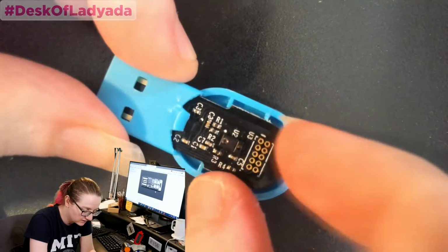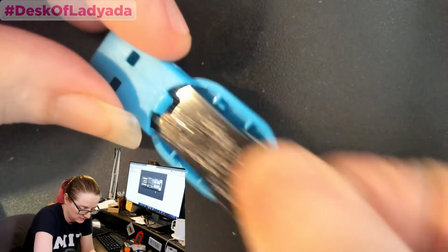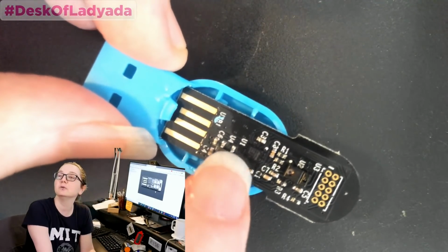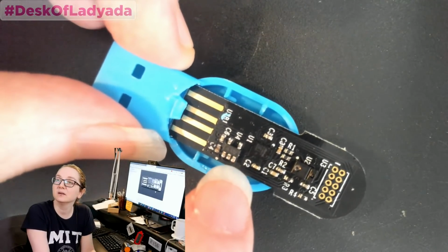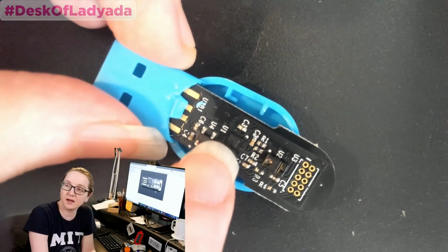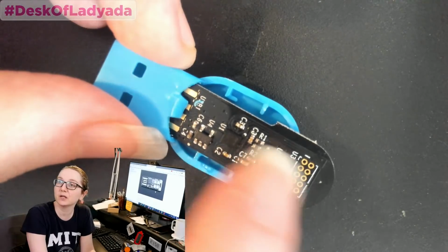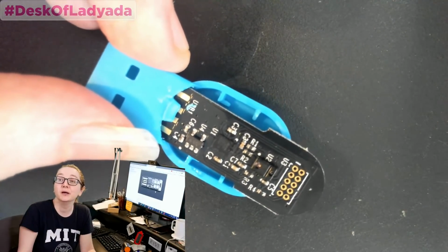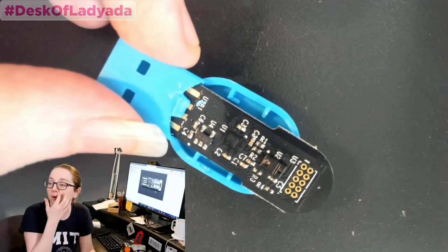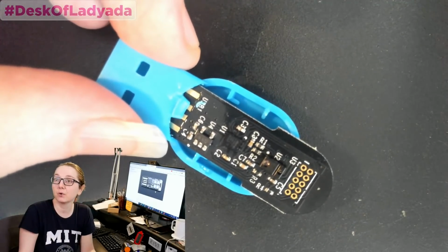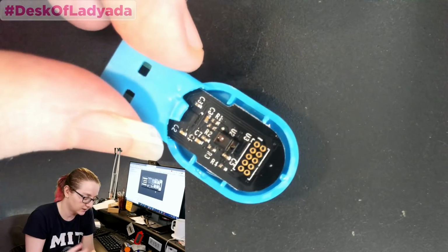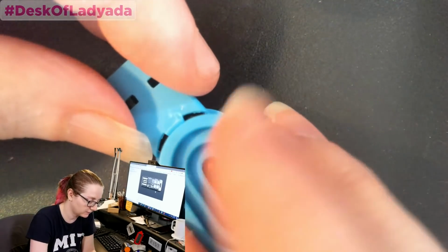And then underneath here, if you pull this up, they use my favorite AP2212 regulator, which is totally overkill. So they probably used it because I use it. And then here is a SAMD21E16. So this is running Arduino code. I know it's running Arduino code because the VID is Arduino, so they didn't change it. They may have used the Trinkey core, or they might have created their own core. I don't know, but it's a SAMD21E18. It's inexpensive, so it makes sense, and it's connected to the APDS 9960 over I2C.